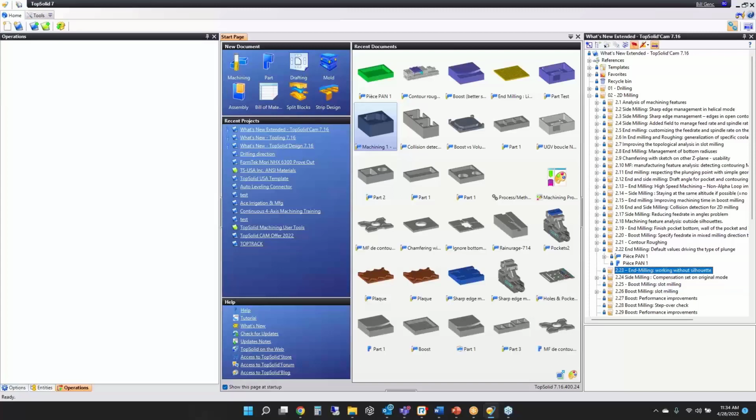For example, in the case of a very high face count part, where the finished machine zones could be defined directly by the selected face. Prior to using this possibility, be sure to check the following. Activate default values, TopSolid Basic, no stock management, or finish environment, collisions, etc. Deactivate the preview of the tool path. Deactivate the graphical preview of the machine zone. The faces to work with on your part are all cleared on the sides, devoid of risk of collision, and they're contouring to find the machine zones by themselves.